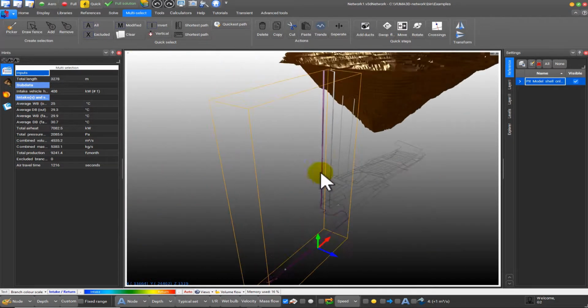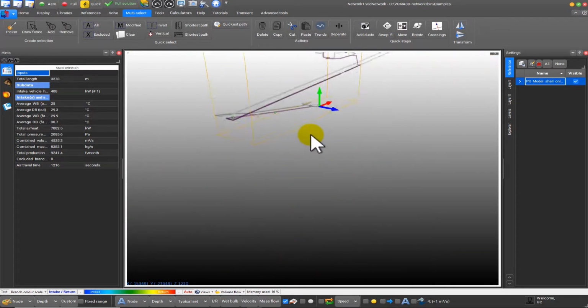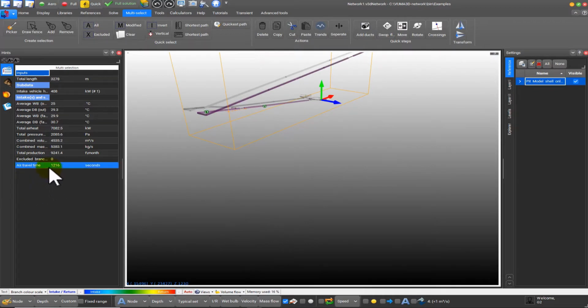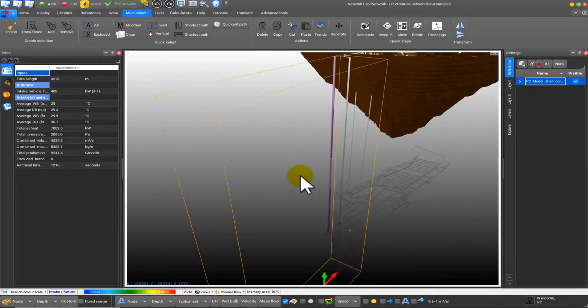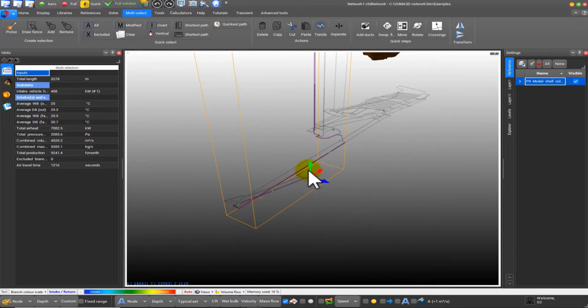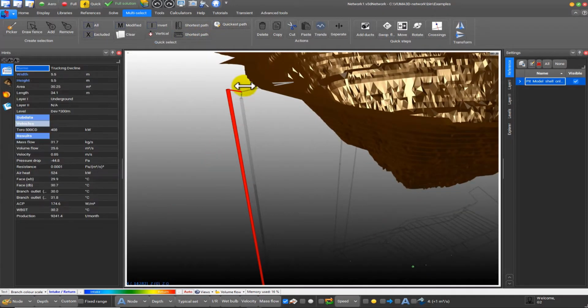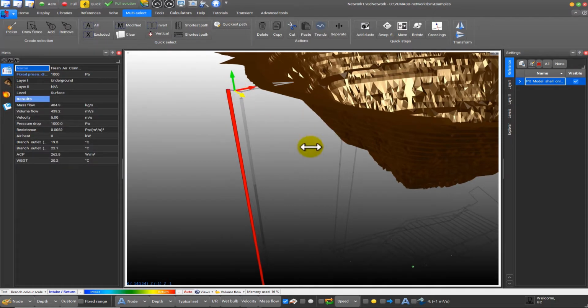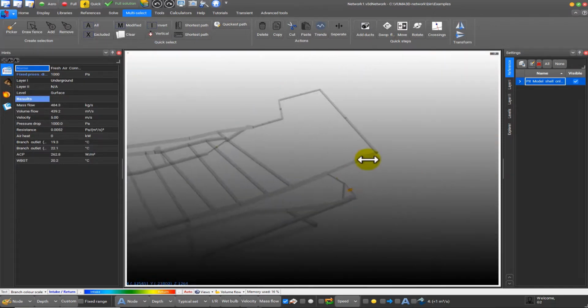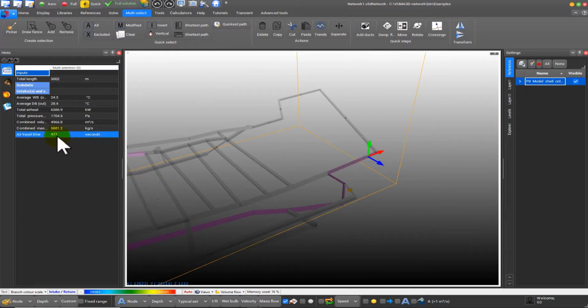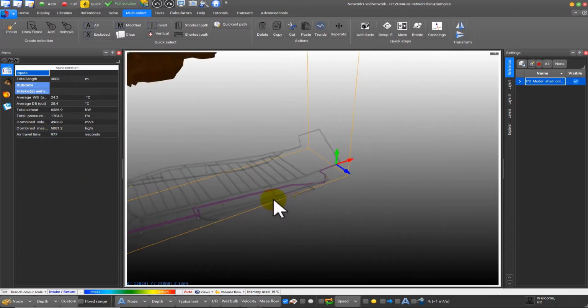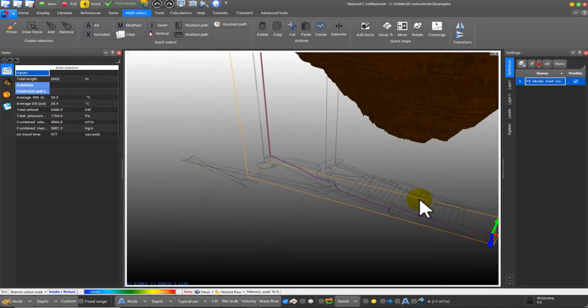Select the path. VUMA finds the quickest air path and it gets to 1216 seconds, which roughly equates to about 20 minutes since release to be picked up over here. If I look at a different spot, I can start again from here, find a point over here, this time about 977 seconds, because it's a much faster route.